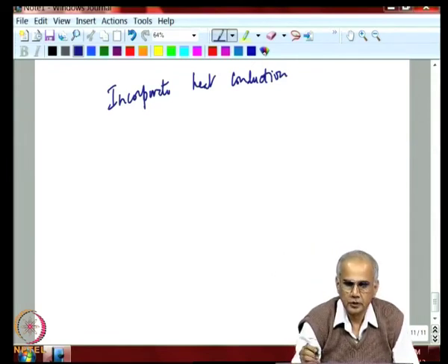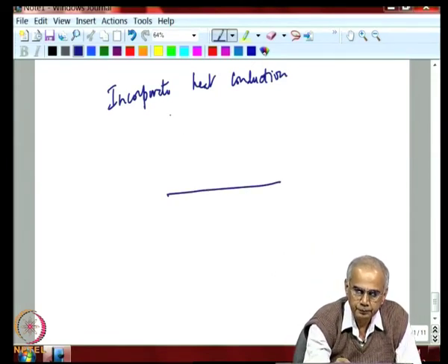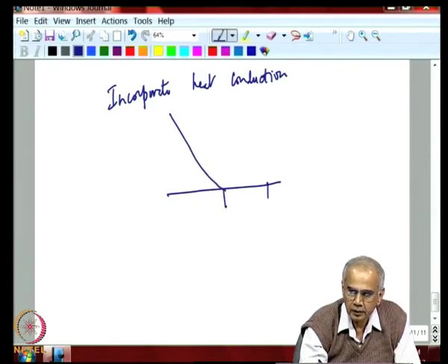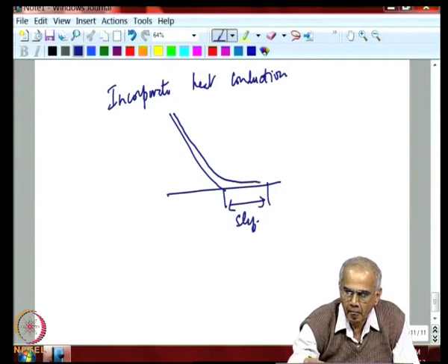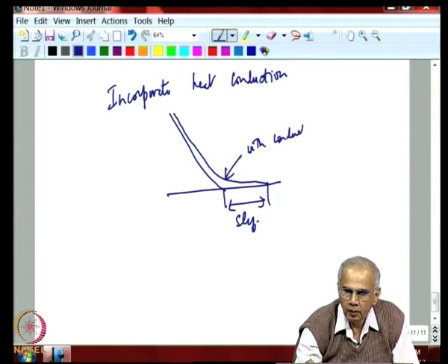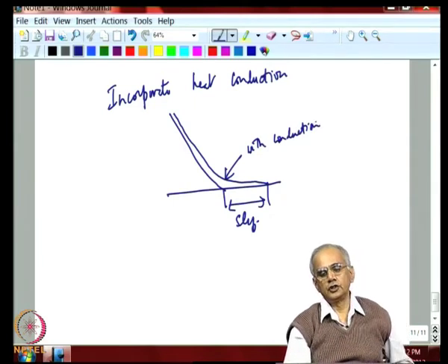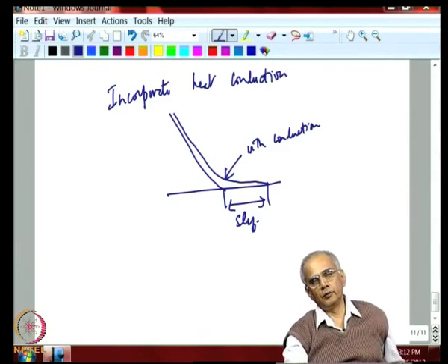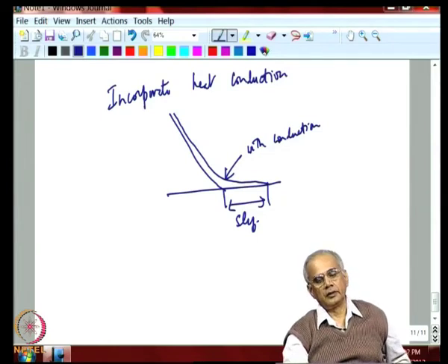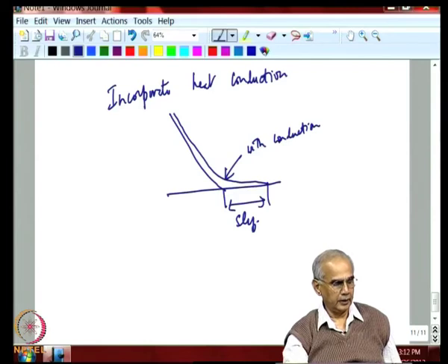So, we expect that the solution we got for pure radiative equilibrium, which had a slip, will now become continuous, and the smoothing of the sharp gradient near the wall will be done by conduction. Conduction heat transfer will ensure that the temperature very near the wall is smoothened by the diffusion process that is inherently there in conduction.